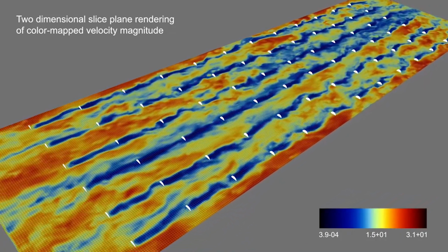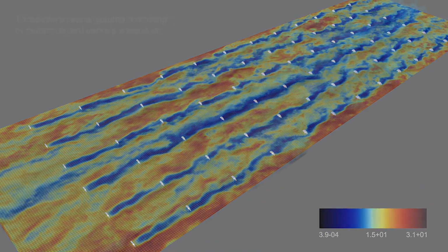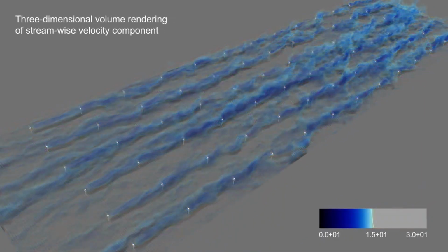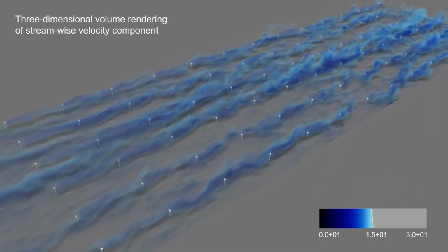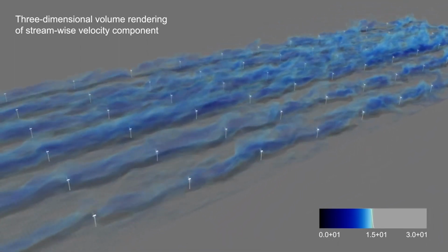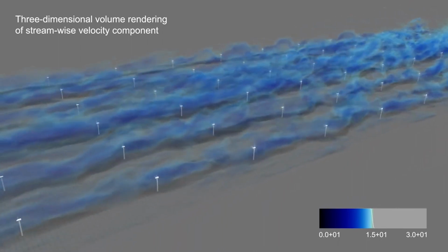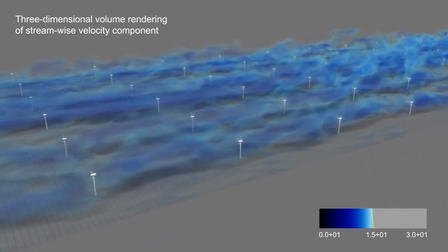Turbulence affects the load distribution on wind turbines and can contribute to wear and fatigue. Turbulence disrupts the smooth airflow over the blades, hence reducing their efficiency in capturing wind energy. This phenomenon is often called turbine aerodynamic performance degradation.